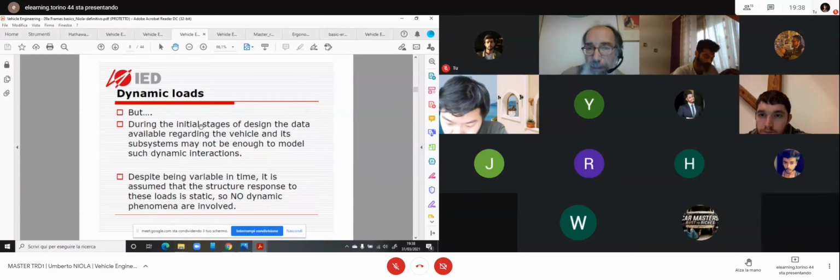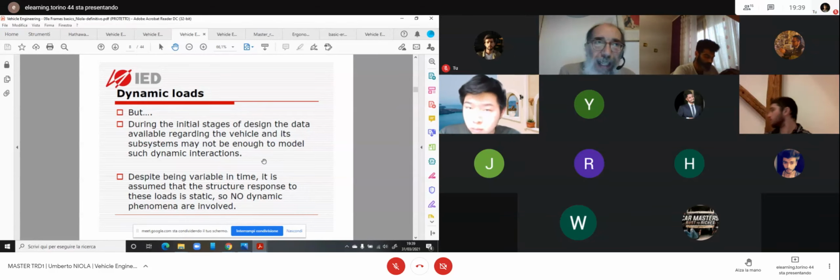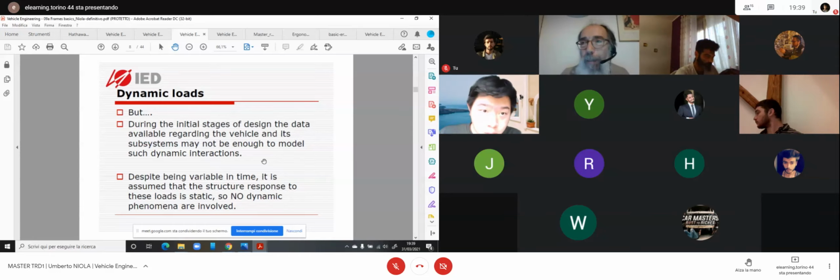In the first part of the design, you have not all the dimension and weight and solicitation possible for the car. Simply the fact you are still designing and dimensioning the parts and selecting the solution and the materials make the difference, because the weight and the distribution of the weight and the resistance are all related to this. But anyway, you have not this kind of application, but you start from some standard definition. You imagine the target for weight, the distribution, and physically the first packaging of the car.